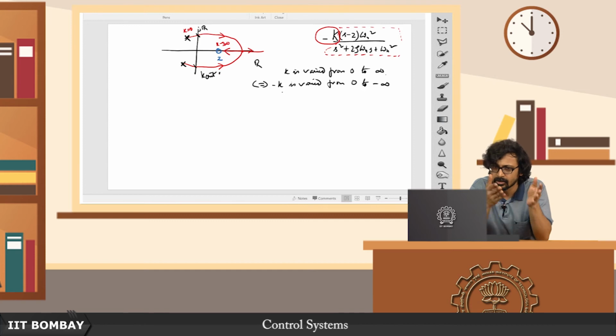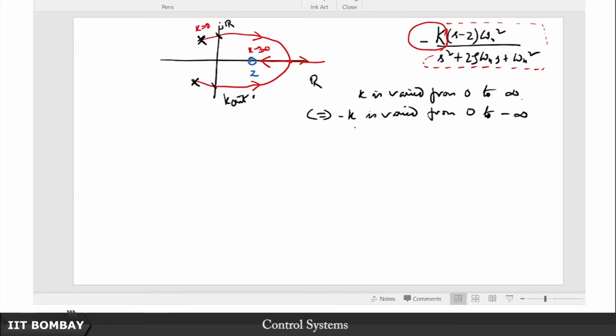Now we have the Routh array and we have root locus, such detailed and sophisticated tools at our disposal. So now we can conclude that in general just having a handle over this k to reduce the steady state error may not be such a good idea, which is what motivates us to seek integral action. Integral action, like magic, gives you 0 steady state error to a unit step, even if your plant is type 0. But even if you say, I am not so concerned about ensuring absolutely 0 steady state error, very small errors will do, so why go for integral action?